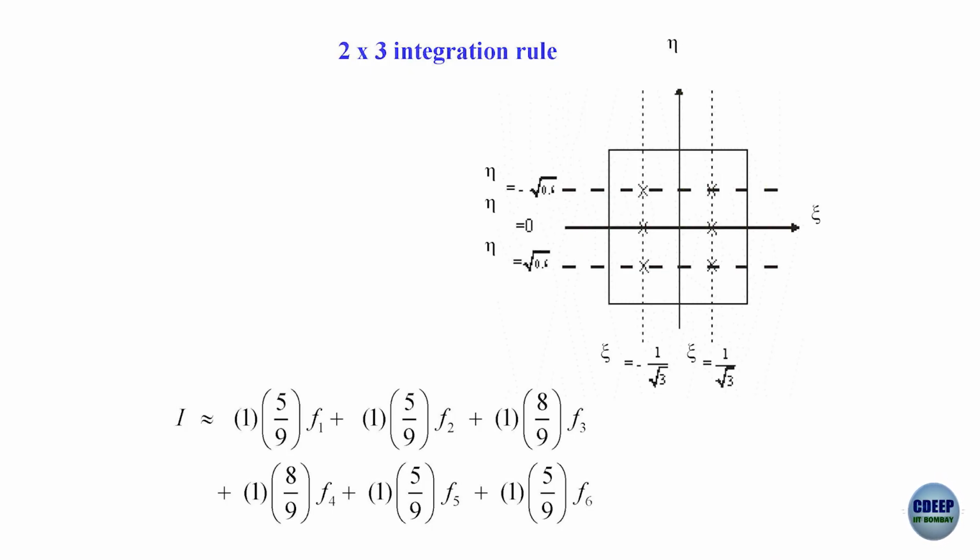So, you multiply these two and keep adding, then you will get the entire stiffness matrix. Okay. So, this is how all the evaluations in zeta eta coordinates are done for the integrals. In your ANSYS, Abaqus, COMSOL, whatever software you use, they would use this.